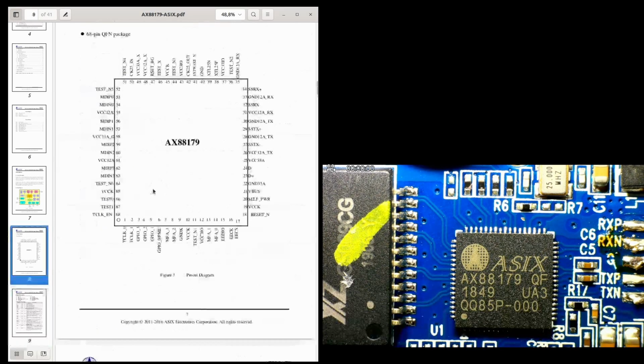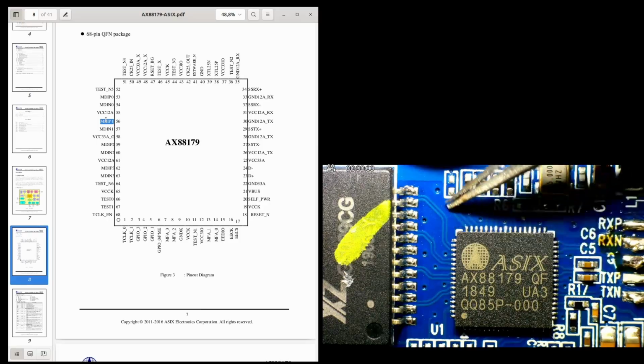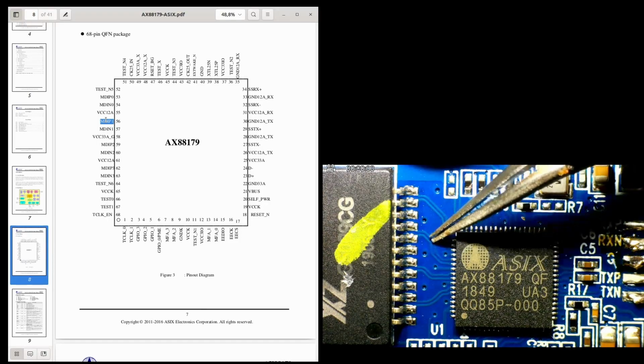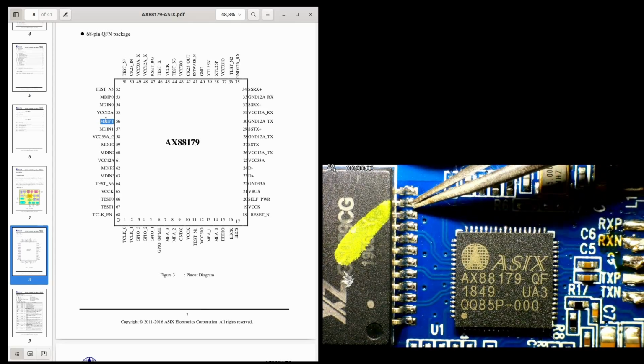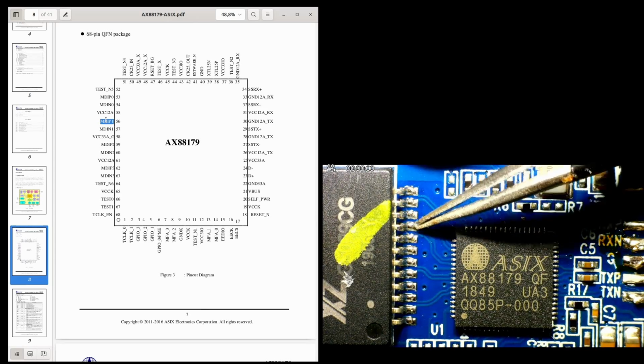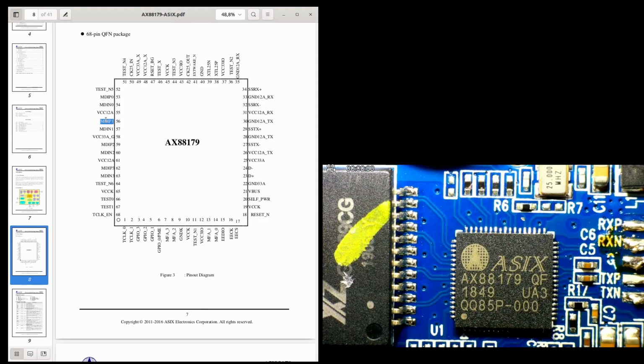If we go to the pinning again, we see, okay, the 0 is the very one on the top, and 1 is the one above. So on my PCB, I can see this already here. That means this is actually the TX and this is the RX line. So we go with our oscilloscope to these differential pairs here. We will test one after the other. All right.